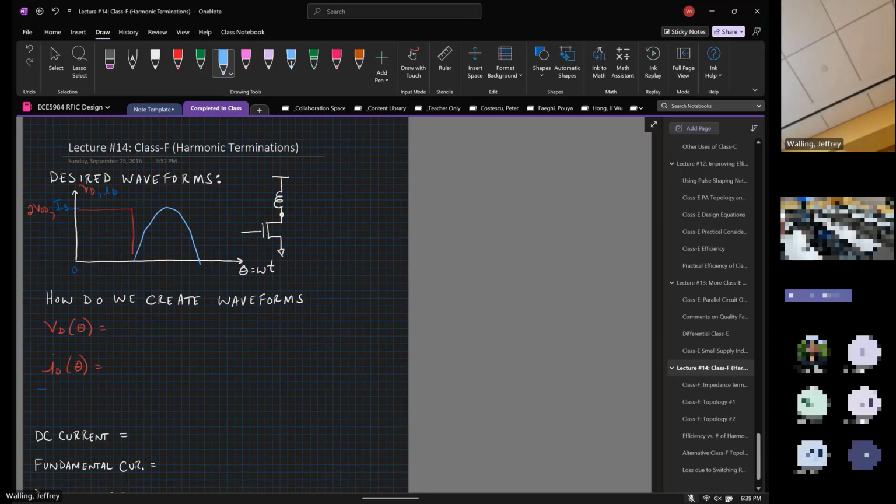I should also say that all of these amplifiers have inverse versions, and what that means is I can invert the waveform. So in the class E that I showed you, where we have that zero voltage switching, I can do the same thing and make it a zero current switching waveform. That would be called an inverse class E network. Do the same thing for a class F network: I invert these two wave shapes, and I have an inverse class F network. Okay, so we will stop there.